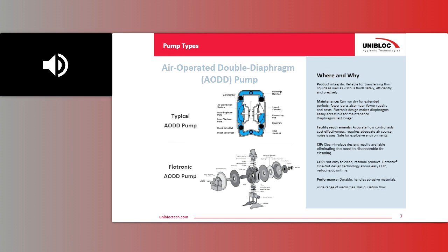We call them diaphragm support plates, to allow you to feed up the inlet side of the pump on the liquid side with up to 100 psi pressure. So that allows you to use that pump and truly CIP it with a separate CIP supply pump, because it can handle the inlet pressures that go through the pump. So basically, when you're cleaning, the piping in and out of the pump becomes part of that piping to be cleaned.